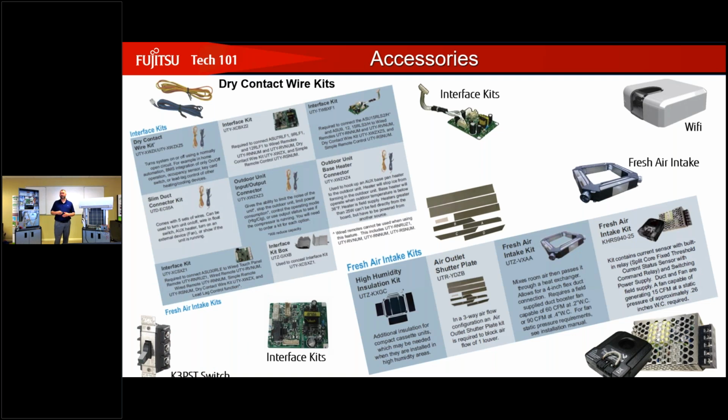I don't know if you guys are using 3-pole switches, but coming soon to a code enforcer near you, you're going to have to install these switches by the indoor unit to kill power in the case you need to service the equipment. A lot of our inspectors are starting to ask for these sort of things, so keep in mind that that may be something that you'll have to do in the near future.